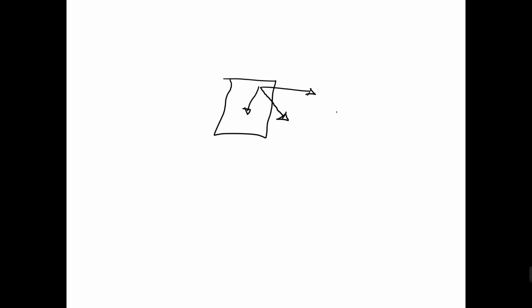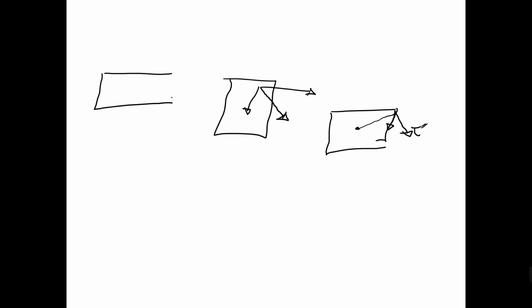Because if this is the center, this is the largest distance, this is the secondary shear, and the primary shear is either horizontal or vertical downward, then to calculate the resultant we need to check the x component of this and the y component of this, and take the square of the x components plus the y components. But in the case of bending, the load is out of plane, the weld is made here, so the primary shear is within the plane and this tertiary shear is always out of the plane. So they always make an angle of 90 degrees.